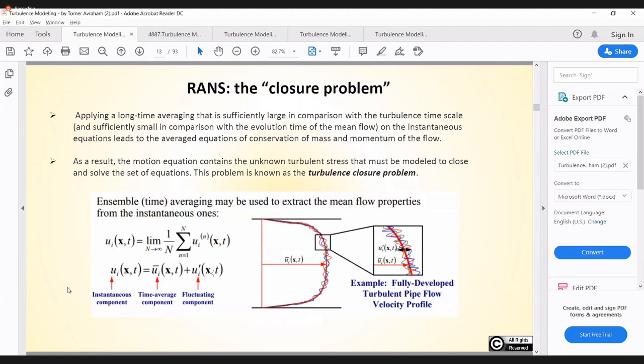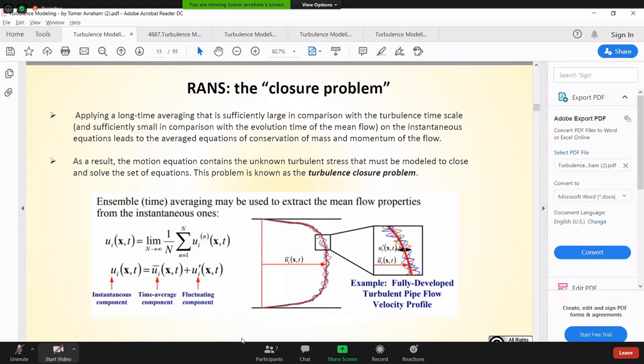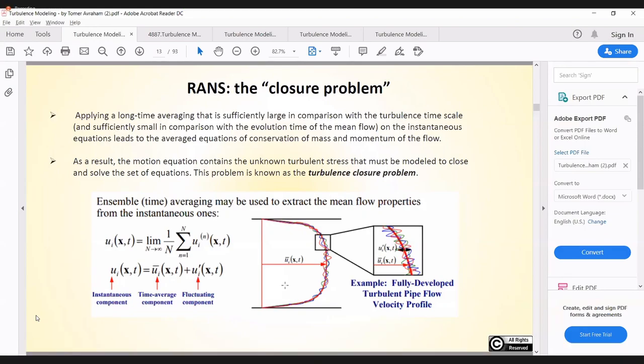Here you see what a sample average is. Even though it's averaged, there is time here. And we assume something which doesn't exist, that we have scale separation. We do have a scale separation between the molecular size and the continuum. When we say infinitesimal and then develop the Navier-Stokes equation, the infinitesimal is a lot larger, so we do have a scale separation.